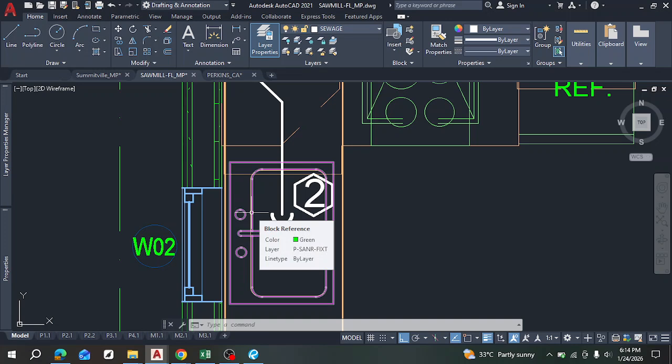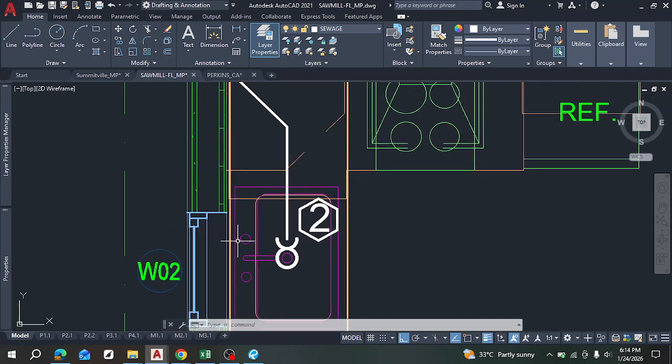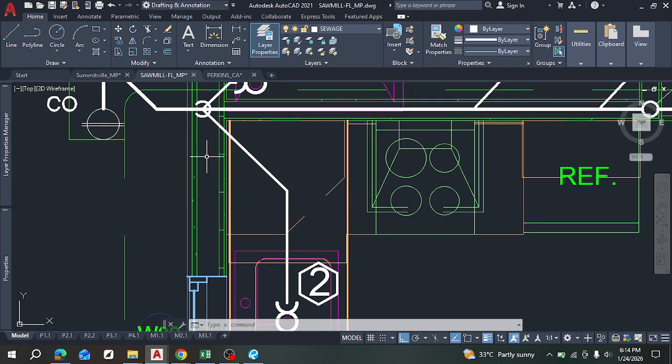to make some changes. An architect may not know that placing a sink directly in front of a window is a problem. Okay, it's not really a problem, but it is a bit tricky to vent, because a vent usually goes up in a vertical line, right? So the plumbing designer can decide to go there, but it won't get to the window. You just travel up a little and then it can continue in the wall. These are different design ideas you can implement, right?